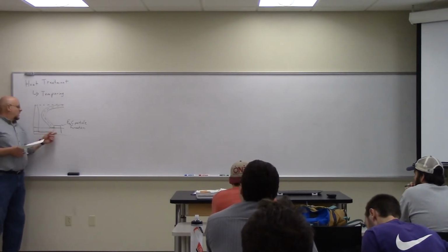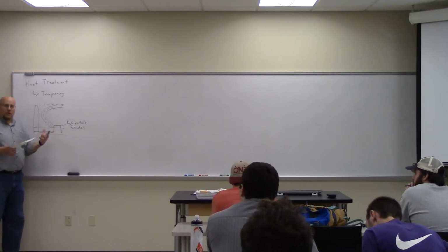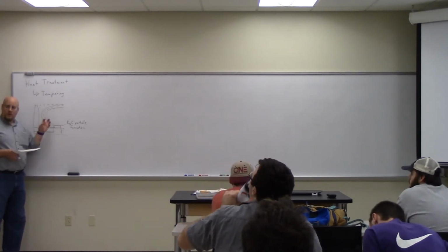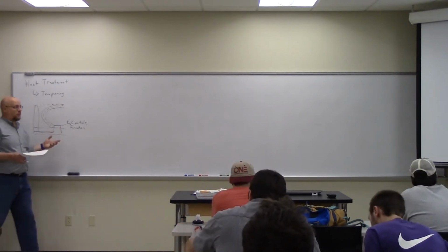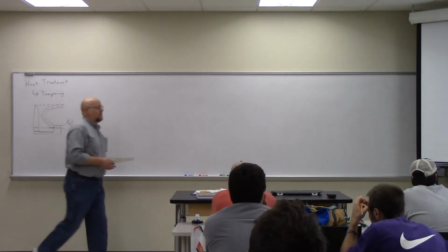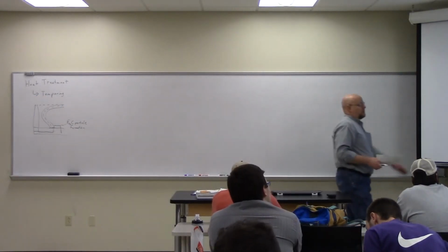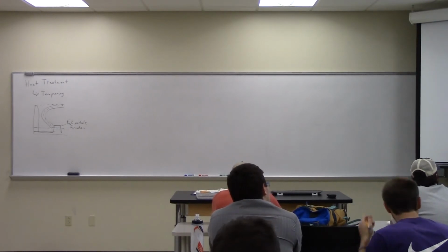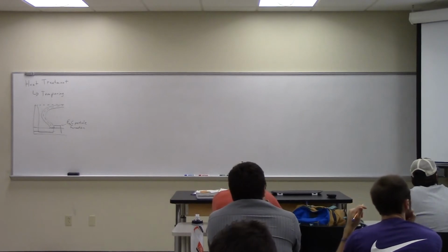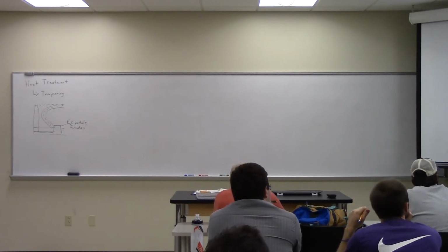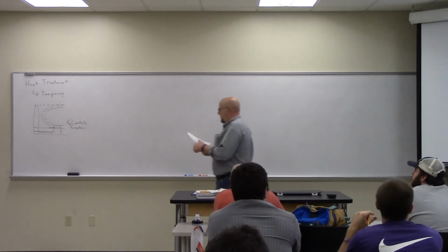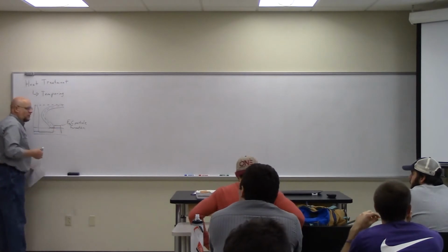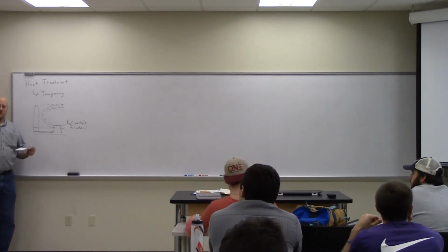But as you warm it up, you create additional thermal energy to allow for diffusion. Now the carbon and iron can diffuse and form little cementite particles, because remember, at the eutectoid composition, down here at room temperature, we're in this bottom range. The steel wants to be alpha plus Fe3C. So you're going to form these little Fe3C nodules or particles, and those particles form to relieve the internal strain that exists in the martensite.